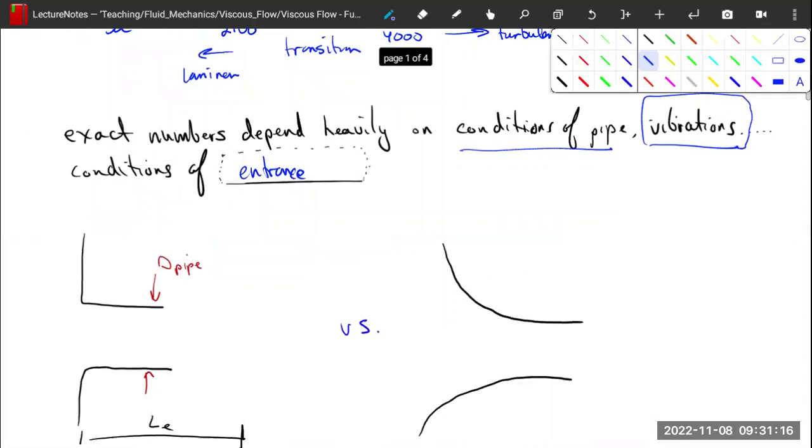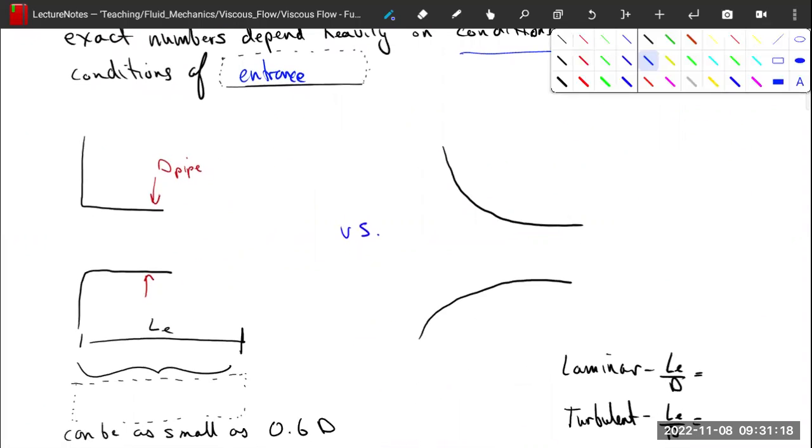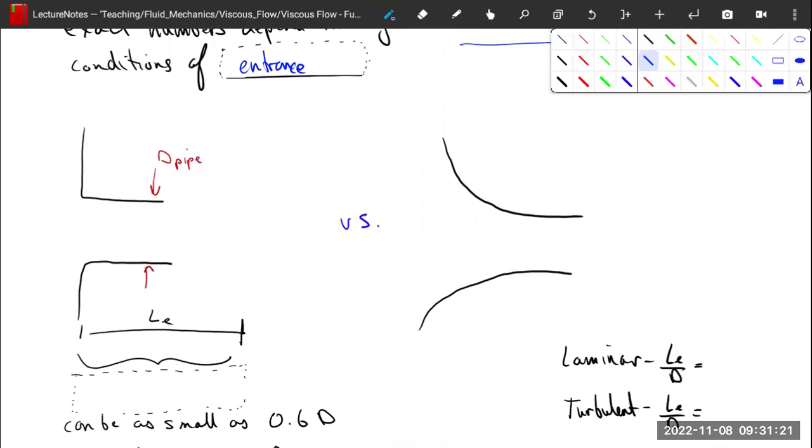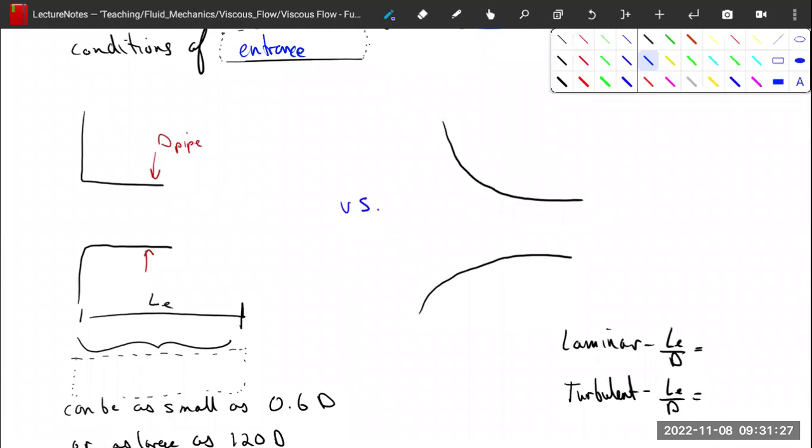And why does the entrance matter? Well, if we look at these two entrances for our pipes here, and we draw our flow, and remember we've talked about this, but flow coming around a corner, when it enters the pipe, we've got a big area here, and it tries to come around this corner, but it can't make a 90-degree turn, right? Fluids cannot do 90-degree turns unless they're going incredibly slow. So it misses this turn. Its momentum carries it past it, and we get a narrowing at the exit here, which we actually talked about when we did conservation of linear momentum. This is just like our reentrant exit for our tank, how the exit is narrower than the actual diameter of the pipe. And then eventually it spreads out.